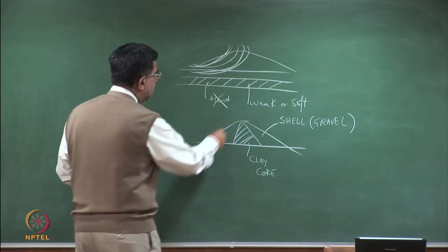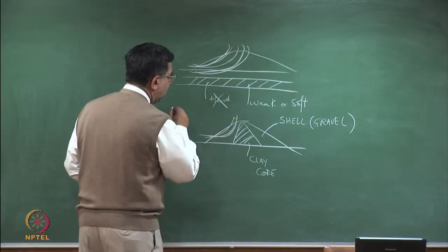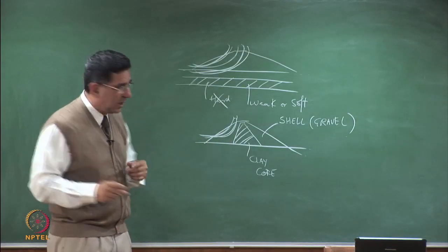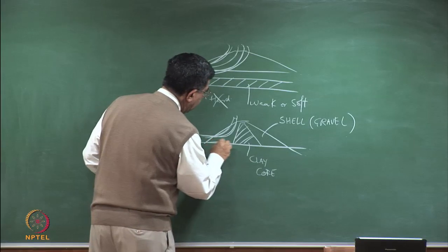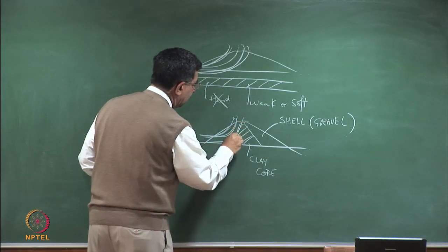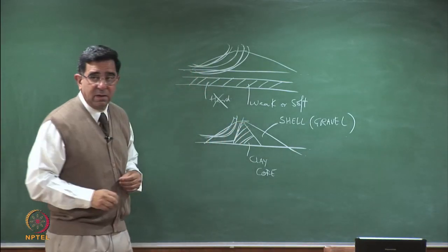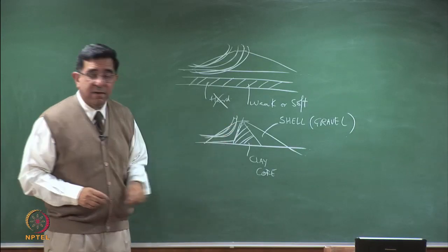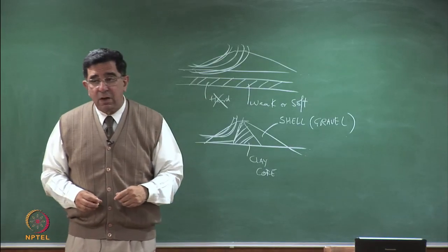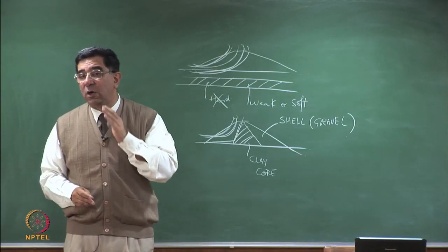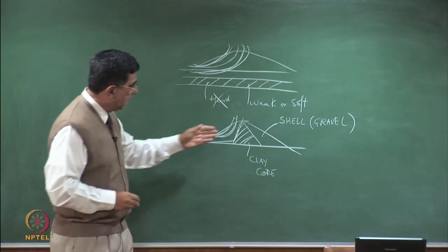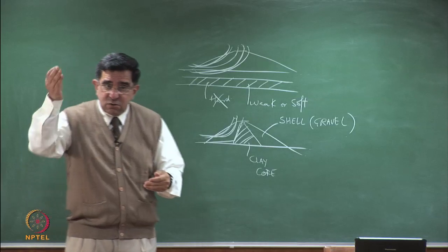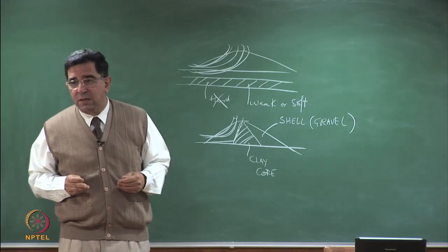You can do your stability analysis like these. So you will get a lot of failure surfaces, circular. But you also should check whether the failure can take place like this. Because when the failure surface is in a straight line, then the failure will be through the clay, which has lower shear strength parameters. This may be the critical surface, this may not. But at least the failure surface tends to go through the softer material.